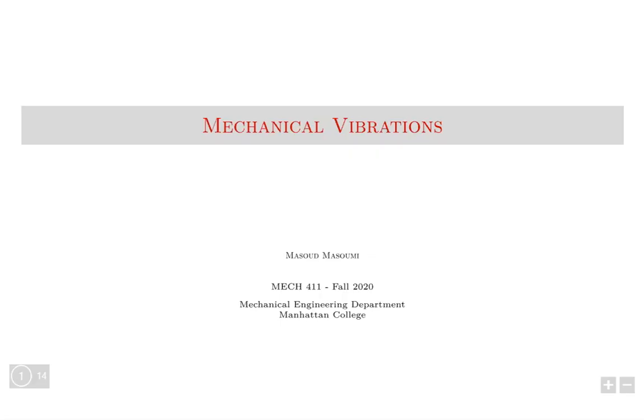Remember, in the energy method, for the most part we didn't have to draw free body diagrams. We were only looking at the system's energy, and using the kinetic and potential energy of the system, we could derive the equations of motion. Now, we'll do something similar for systems with 2 degrees of freedom, and that falls into the Lagrange method.